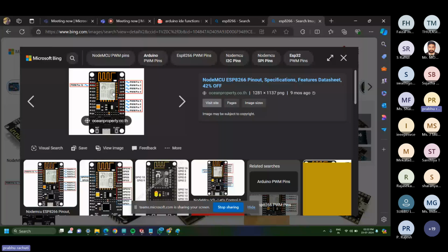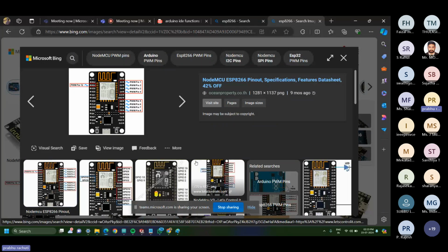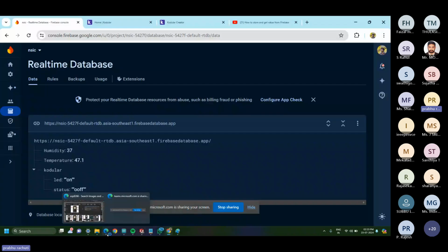Most of the boards in the market come with their own programmable IC. On the screen I'm showing a board image of the ESP8266. This board also has the same kind of IC, which represents the serial debugger. The serial debugger is a mediator between our PC and our main chip. This is our main chip, which has the name of the chip and versions, and the main chip needs a programmable driver IC to upload the code, acting as a mediator between our PC and the microcontroller.